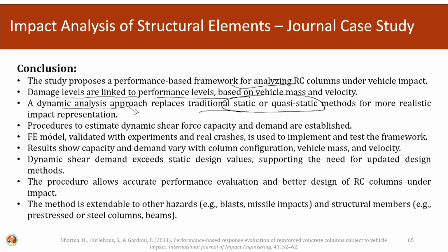So, we established the procedure to estimate the dynamic shear capacity and demands. The finite element model we validated with experiments and the real crashes, and it is implemented to test our framework, and the results show that the capacity and demand vary with the column configuration, vehicle mass and the vehicle velocity. Basically, they are a function of the forcing function and they are a function of the internal configuration of the system also. The dynamic shear demand exceeds static design values.